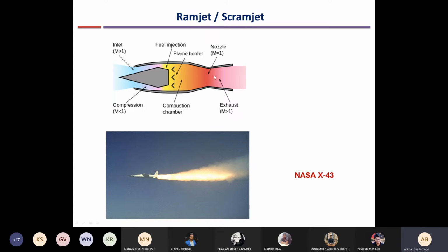Turbine blades, the main problem was not that the turbine blades will melt. We will study later. The main problem is that they are rotating at high speed, and because there is so much centrifugal stress on them at high speed, they tend to elongate, and this happens much faster at a higher temperature. This is known as creep, and that was the main problem.